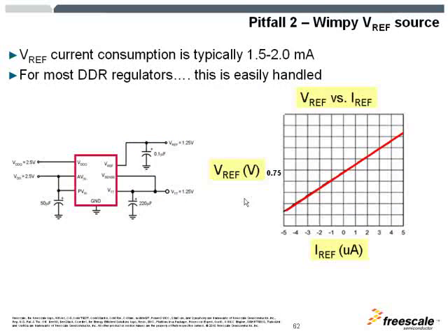So here we're discussing that you should not use a VREF DC-DC generator that does not provide enough current. We do have a spec in our hardware spec that specifies the amount of current that is required for VREF for each device. So make sure that has been observed.